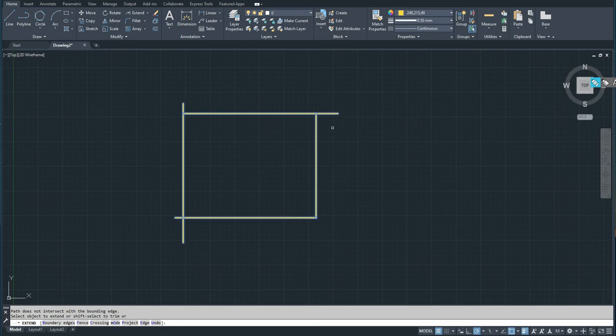What about the trim, guys? If you want to trim now, by the way, guys, I'm currently using the extend command. Extend is still working. In this case, guys, press shift and select this corner to make trim. That means if you are using the extend command, shift with click will make trim. If you are using the trim command, shift click will use extend. Okay, that's it.